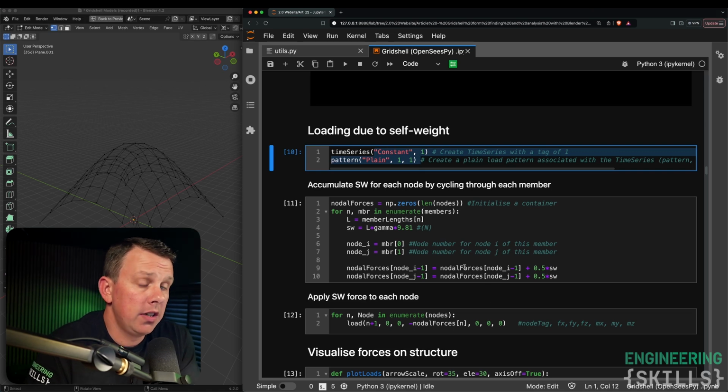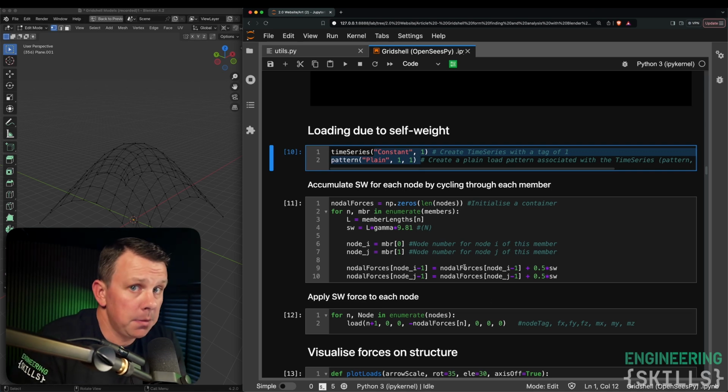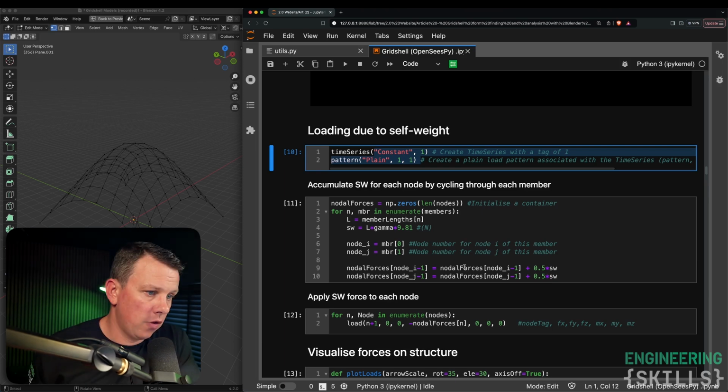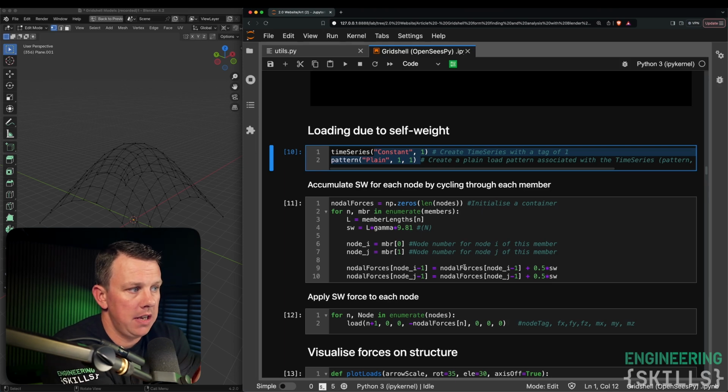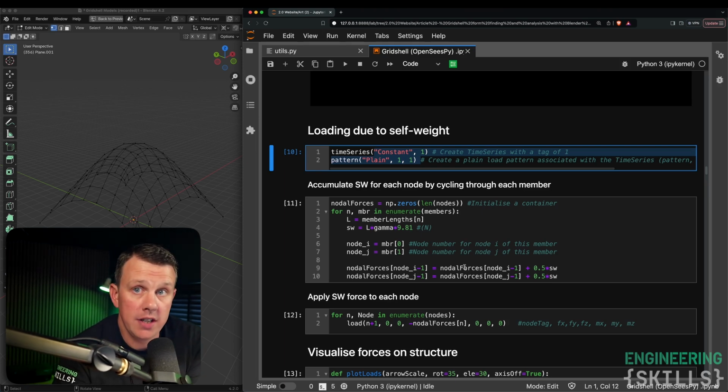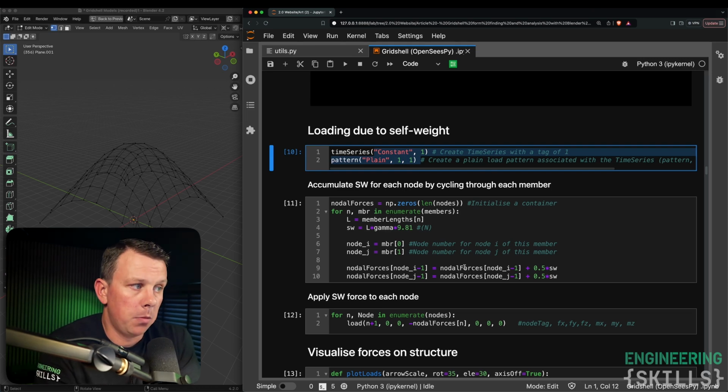Now, the loading is going to be self-weight. And that's important because the geometry of our structure was established for self-weight, essentially a hanging chain, and we just then inverted it. So we would only expect that structure to be in a state of equilibrium under its own self-weight. Of course, we've locked all the joints now, so it could take point loading at arbitrary locations potentially as well.